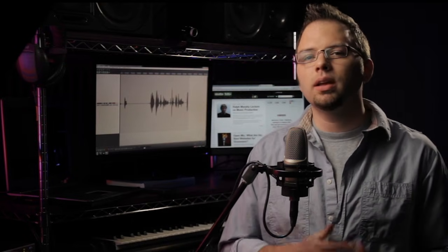I would recommend that you record everything in 24-bit if you can. In summary, sample rate provides frequency resolution and bit depth provides amplitude resolution. Ultimately, you will have to choose your settings, but you will want to consider the storage requirements versus the perceptual differences of these settings.